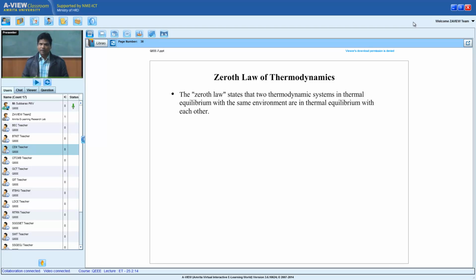People say that when you are talking about two bodies, why are you bringing in a third body? Most of the time in general engineering, though I have one thermometer and one body, and I am trying to have a physical contact, you can't eliminate a third body such as an air gap. If the air gap is large, even if the contact is otherwise perfect, the thermometer will read wrongly. Why? Because I ignored the fundamental fact that between the two systems there may be a third system, the environment, which I want to avoid. If I cannot avoid an environment, it is better to have a good environment.